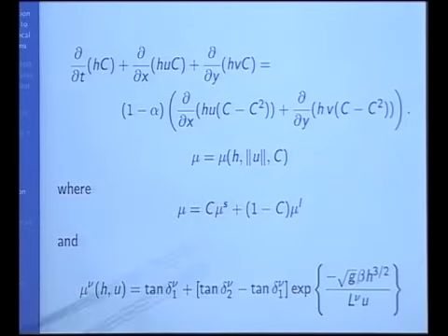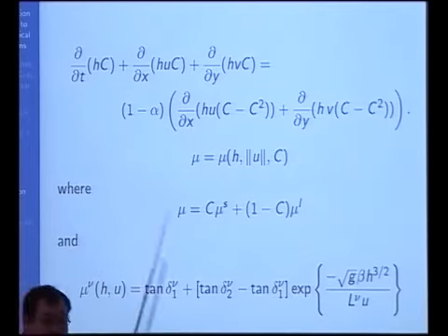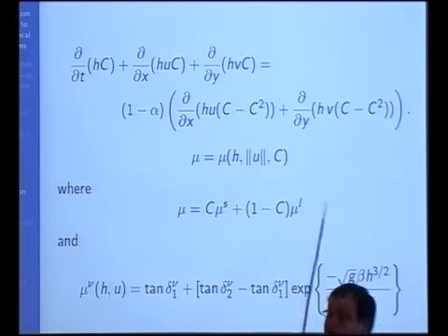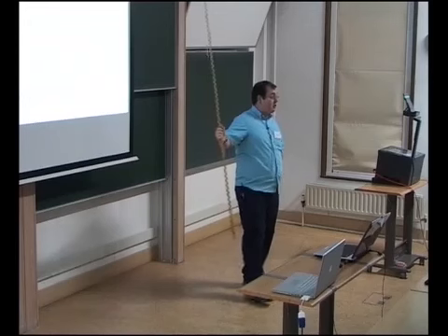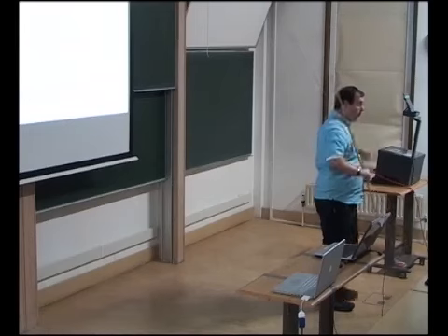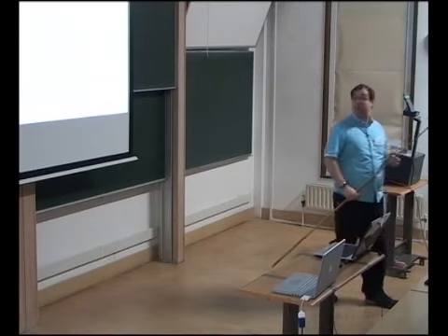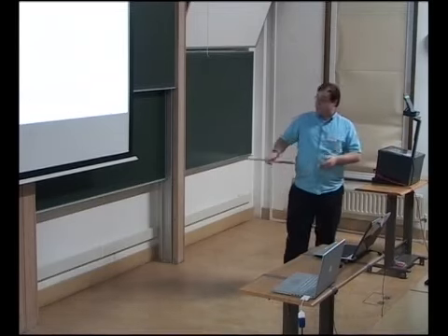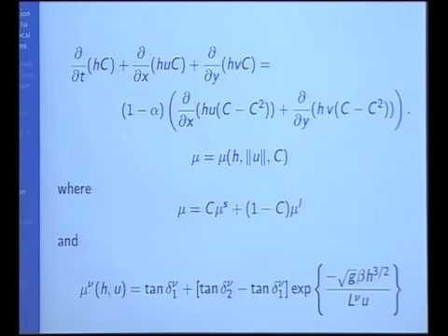Here mu is going to be a linear combination of two friction laws, where C is the depth-integrated concentration, but this is the difference: our C is taken from this equation, where U and V are the velocities from the shallow water style model. So now we have this fully coupled system, which does segregation and shallow flow.